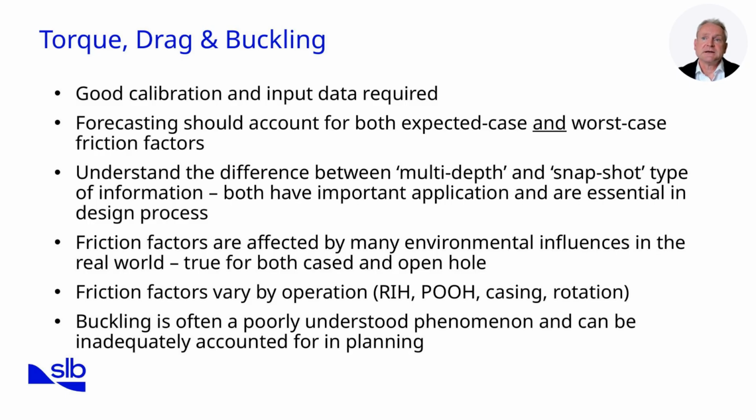We must understand the difference between multi-depth models and snapshot data. Snapshot calculations give a quick view of loads, while multi-depth models simulate the entire wellbore. Both are valuable in planning. Friction factors are variable. They change depending on the hole condition, whether it is cased or open, and the specific operation being performed, such as running in hole, pulling out, rotating, or running casing.